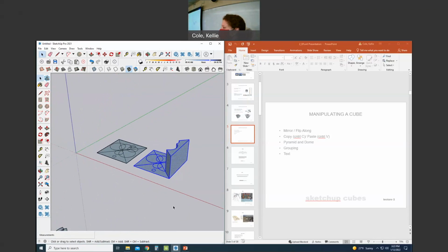We're going to use a lot of buttons today because there are not keyboard shortcut commands set up in SketchUp. I want to rotate this. Q, which makes no sense, is the keyboard shortcut command. Q is rotate. Or when you hit Q, you'll see those two arrows that represent the rotate button.